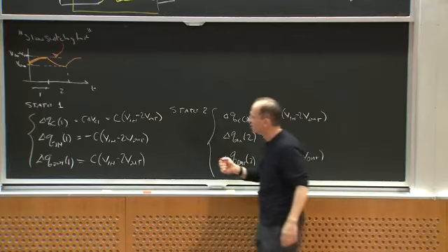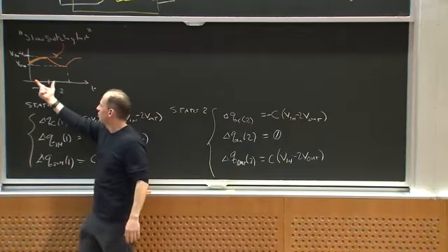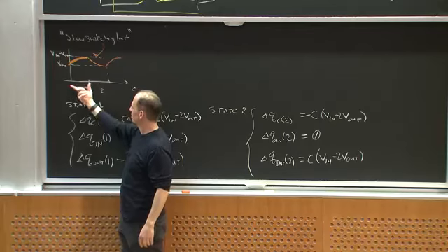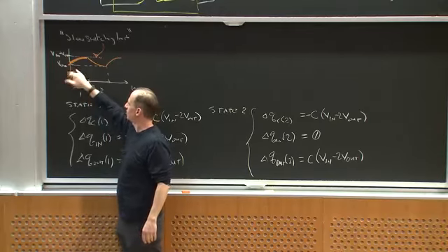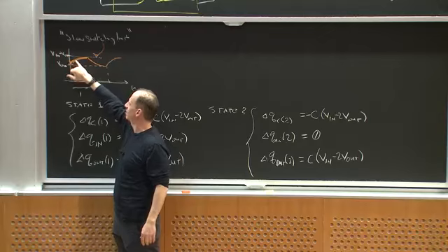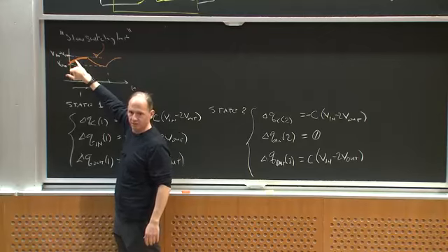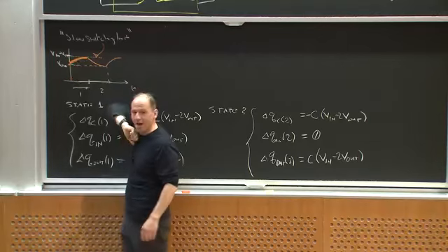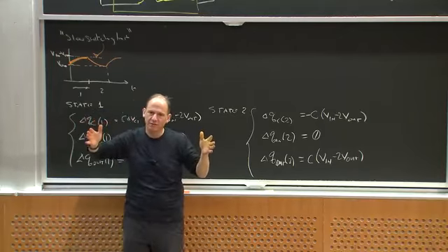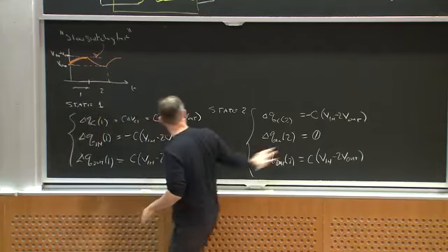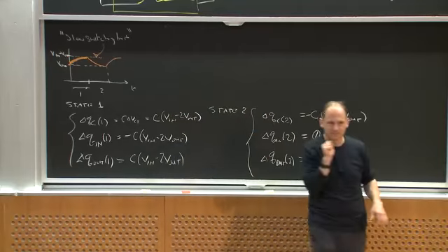But eventually I get to the point where if I increase my switching frequency, suppose I just keep cutting each time period in half, that this time period is going to get so short that my capacitor doesn't fully charge up. And it doesn't fully discharge, right? If I keep pushing my switching frequency up enough, I'm going to violate the assumption under which I did this analysis. Okay?